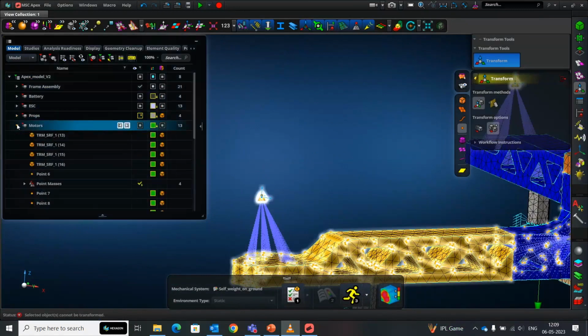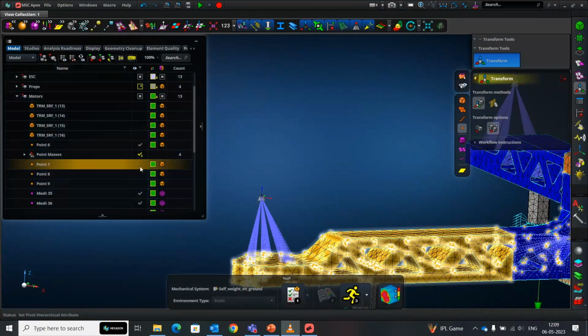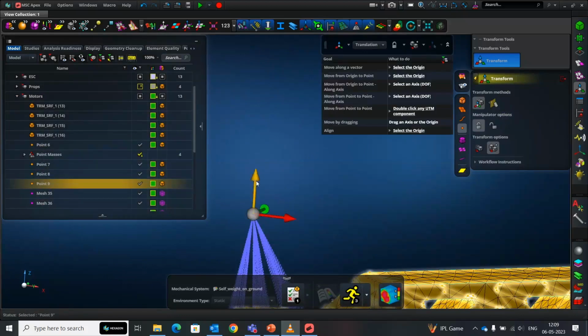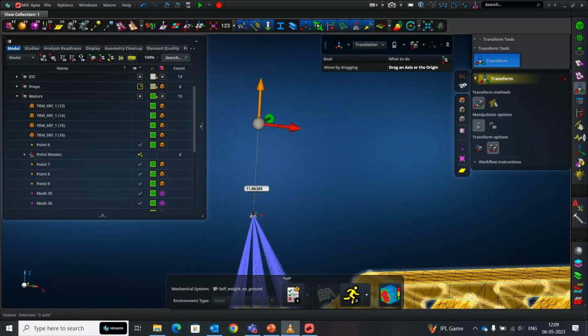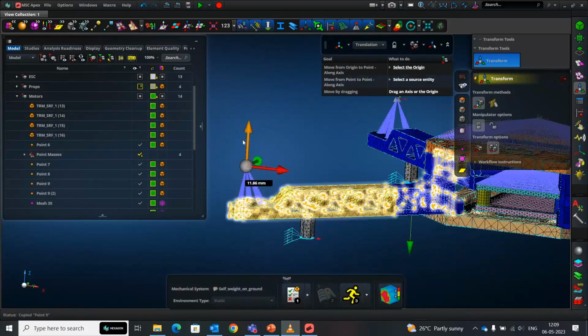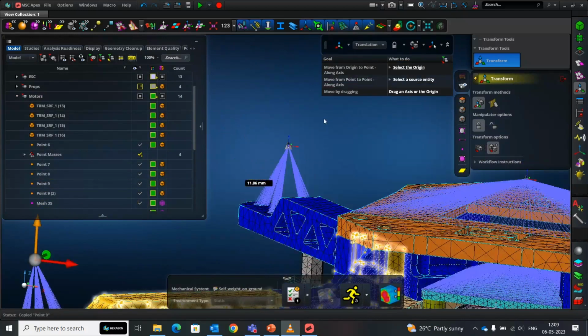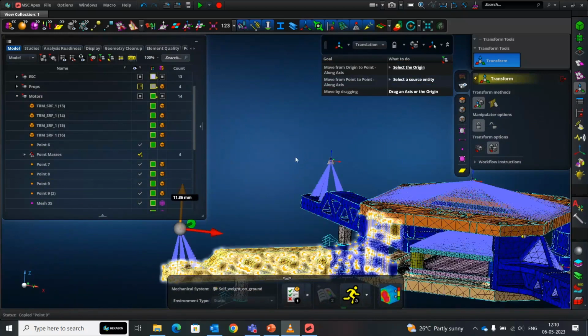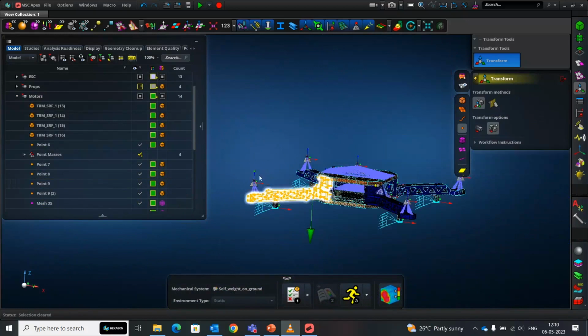This may be different in your case, depending on whether you have a tractor type or a pusher type. So you may want to see where you're going to get your thrust from, a particular location. But I've made an engineering approximation that it is in fact going to be coming from the base of the propeller. That is where my thrust is going to be coming from.